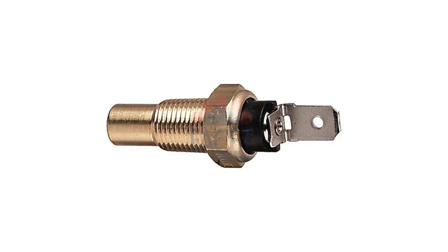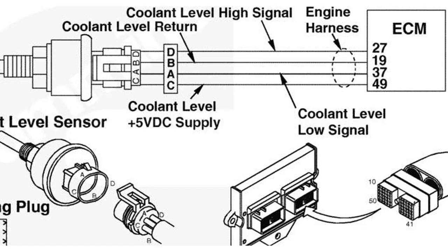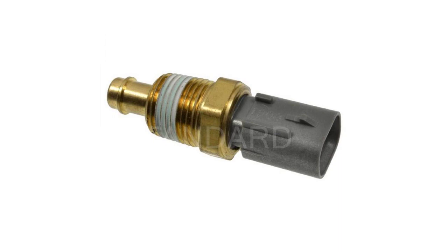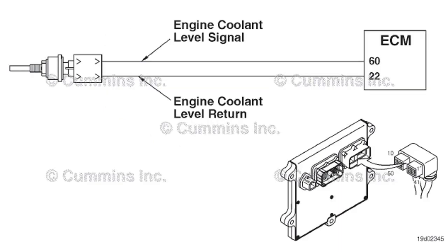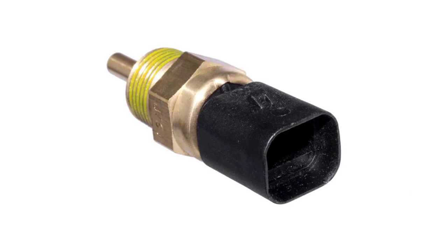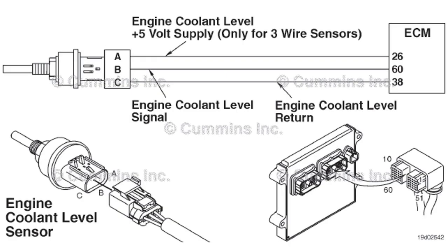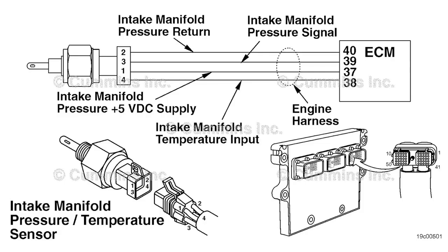This means that the engine's EGR system is experiencing a lower than expected differential pressure between the inlet and outlet of the EGR cooler. This can be caused by a clogged EGR cooler or a malfunctioning EGR valve. The engine may experience a loss of power, increased emissions, or decreased fuel efficiency. It is recommended to have the EGR system inspected and repaired by a qualified technician.